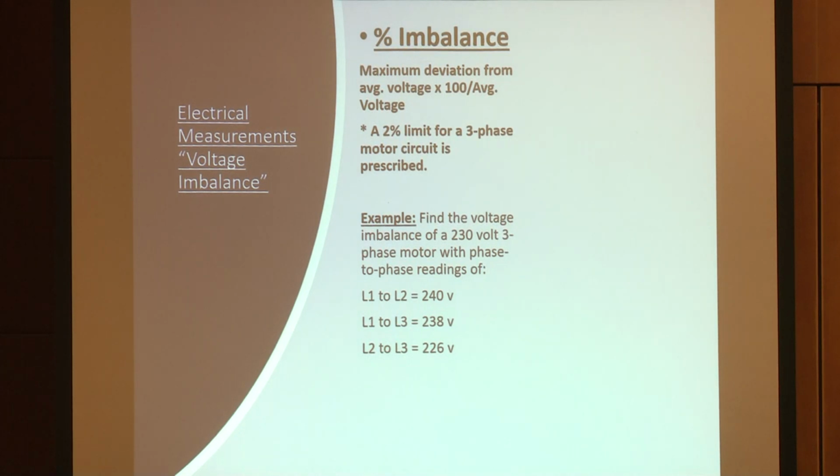Now, some people think this is not important, but I'm telling you, I have a lot of jobs that have electrical problems based on imbalance. And so when you start having those problems, the owner now has to buy a lot of expensive balancing devices in order to balance the power. So you need to make sure that you do this right and you give the owner good advice so that they don't have to go out and buy very expensive equipment.